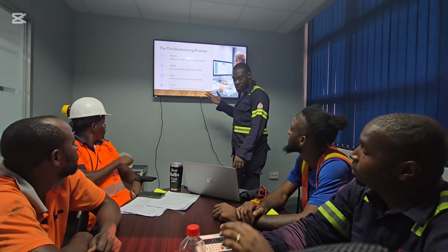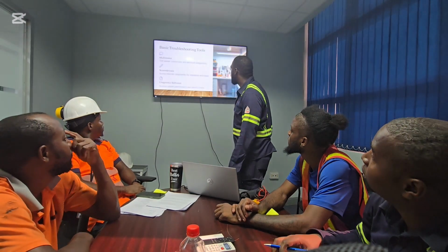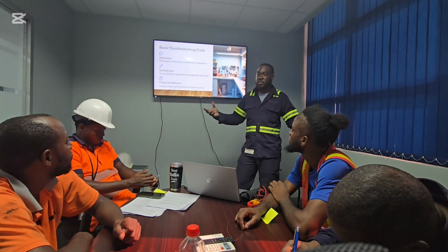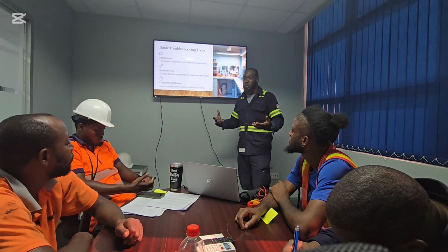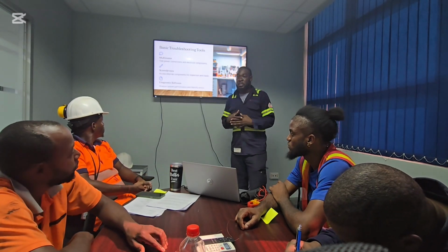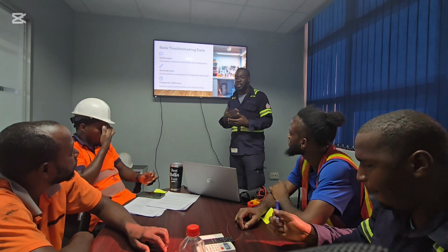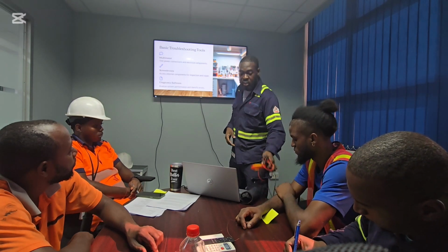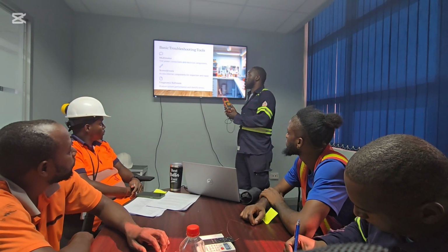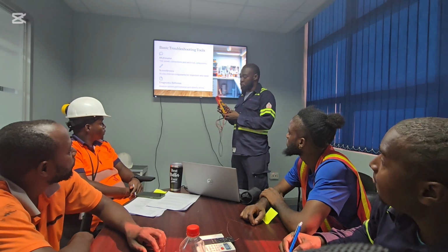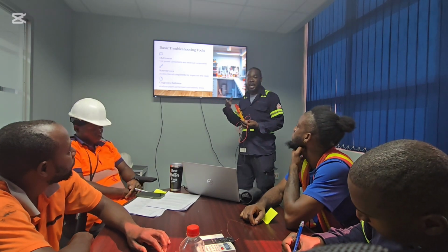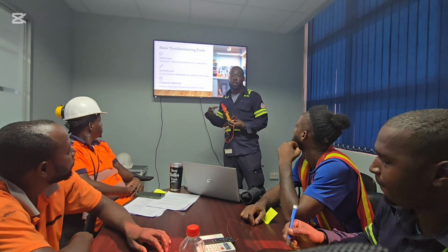Now, after the troubleshooting process, we're going to move on to basic troubleshooting tools. Now, doing troubleshooting, we can't just go there and look at equipment and expect it to fix itself. We have to work with some basic tools. So now, a multimeter is a very popular tool that we use to diagnose electrical components or electrical circuits. Now, this is a clamp multimeter. Based on what you're looking for, you could check for the amperage, the resistance, or voltage of whether AC or DC. It depends on the circuit that you're working on.